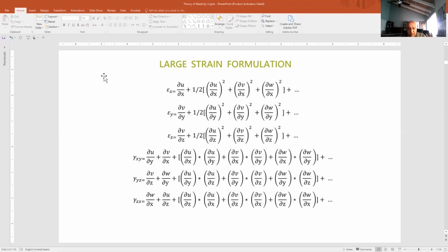But if we mistakenly, for example, assume large strain and use these equations in place of the small strain, we should come up with the correct solution. Okay. On the other hand, if the small strain is not the correct assumption and should have been a large strain, if you use the linear system and small strain condition, then your solution wouldn't be accurate. Okay, thank you. Okay.